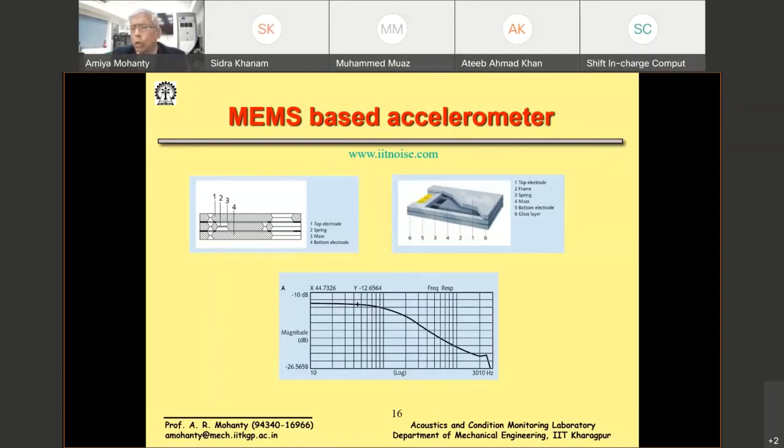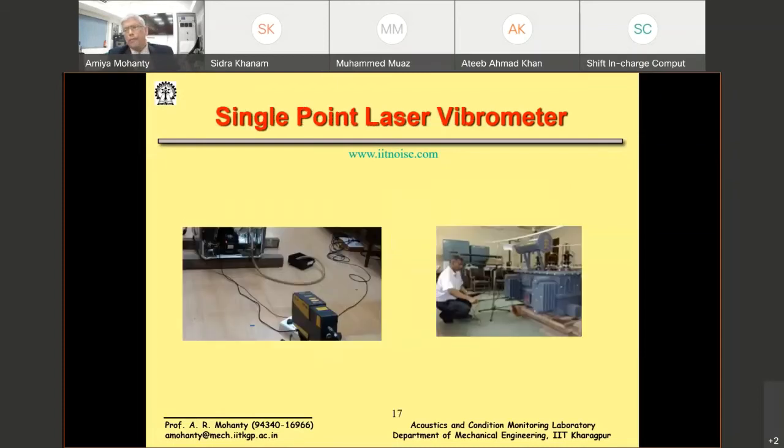And shock detection accelerometers for deploying in something. These are very, very popular. Okay, limit type accelerations. But for actual condition monitoring, one restriction is the frequency, the other is the temperature. But having said that about accelerometers,